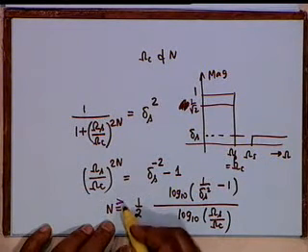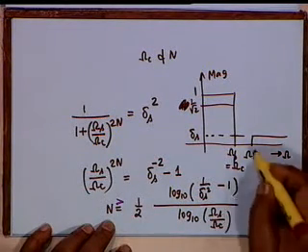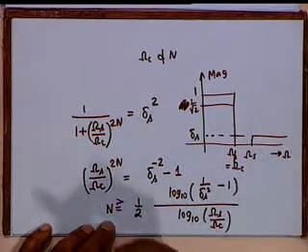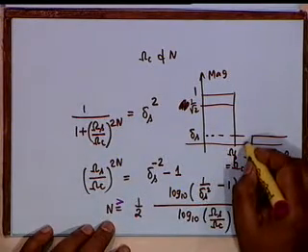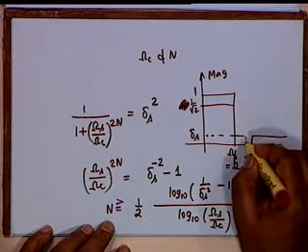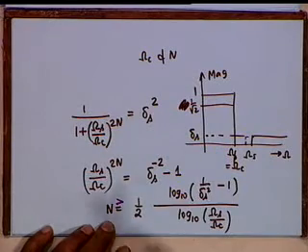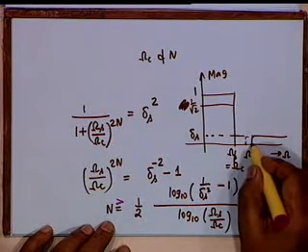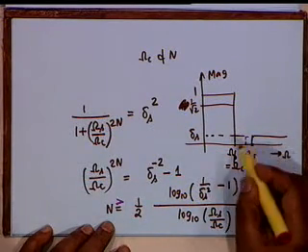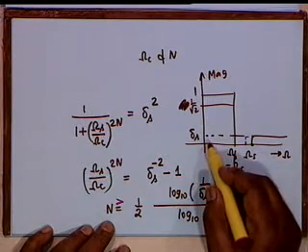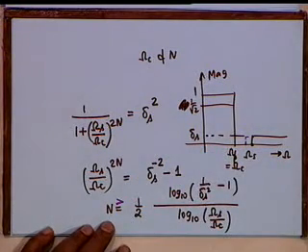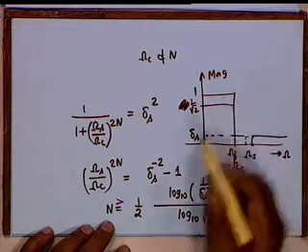If capital N is greater than this, then obviously the actual omega s that you shall realize will be somewhere here. In other words, the stop band is pushed to the left, and what you wanted, the attenuation at omega s, now shall be less than delta s, which is a welcome feature, but you must not play with the stop band.